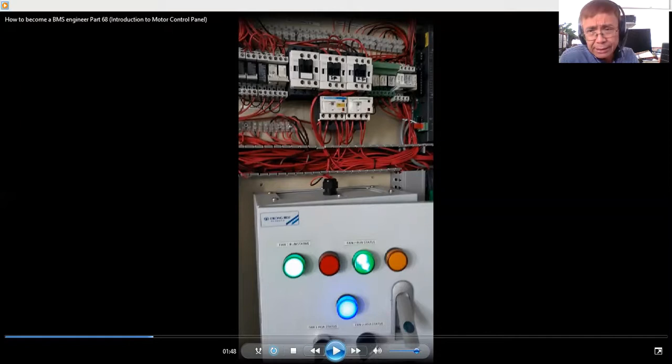So it is already programmed in one of my controllers, the operation of this twin exhaust fan, because when I put it in automatic, then immediately one of the fans runs. So the program downloaded to the DDC controller is already working. My control logic program does not detect any trip condition or any other condition that is included in my control program.